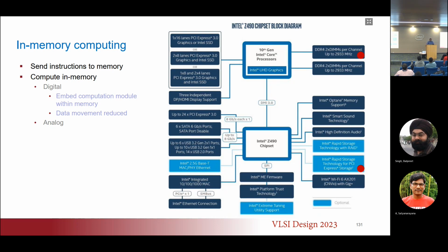So instead, when they do a search operation on encrypted data, they just send the search query word to the memory. The decryption engine sits inside the memory, in the DRAM space, and it does the decryption and the comparison there and gets the result back.